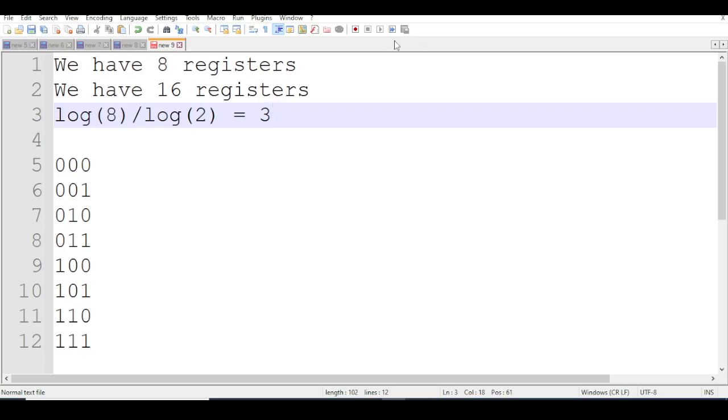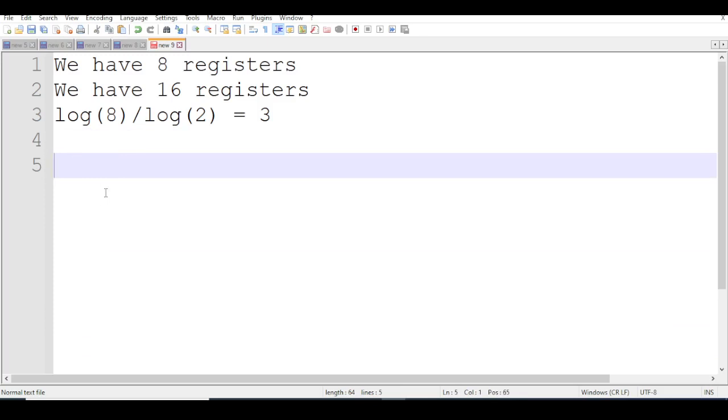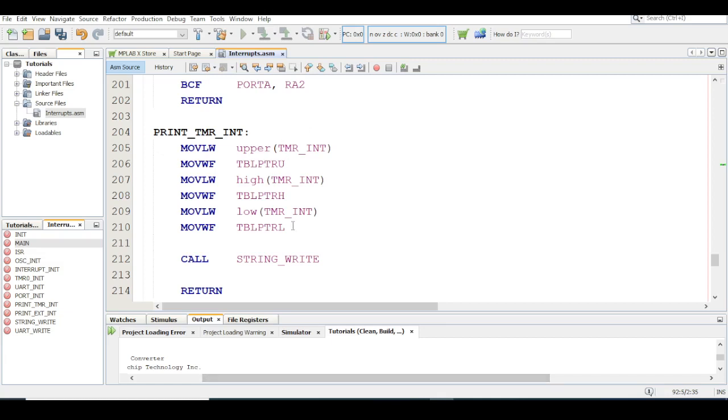So at some point the PIC program memory has so many registers that what's required for this is actually 24 bits. So these 3 registers right here is 24 bits for the PIC. I'm not gonna type that out. But the way to access these registers, it's broken up into 3. So TBLPTR...